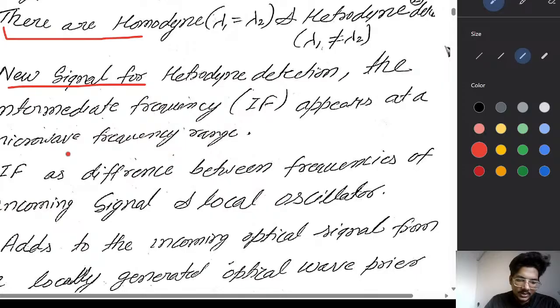A coherent optical communication system is one in which the received optical signal is mixed with a locally generated laser signal. The mixing allows the receiver to detect the amplitude, frequency, and phase of the incoming optical signal, not just intensity. It gives high sensitivity, long distance, and higher data rate.